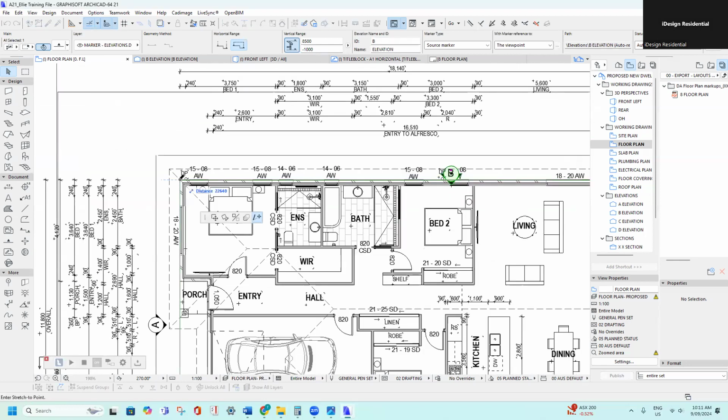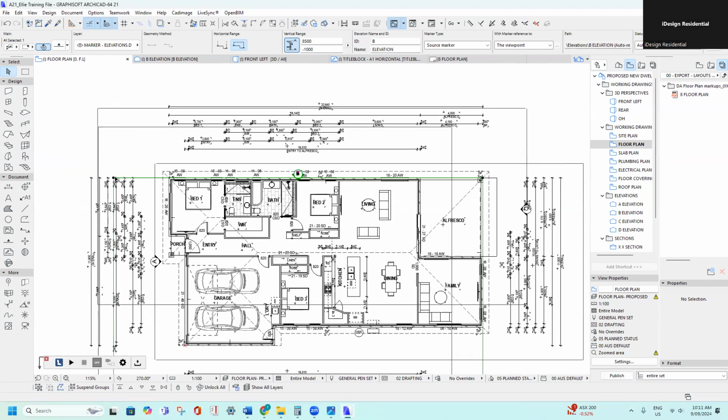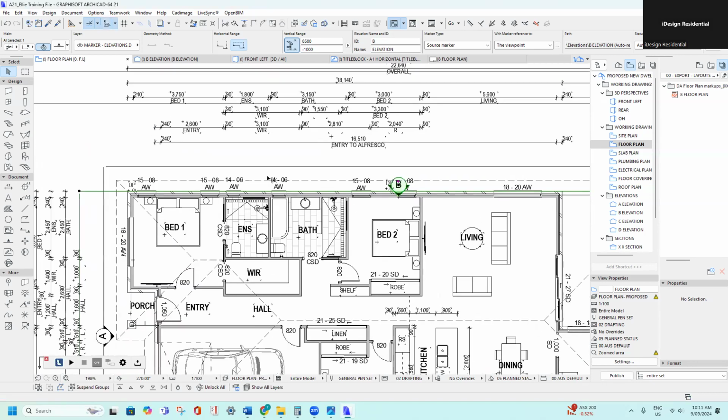and then I add in an extra 4 meters. So you can see the distance is showing 22,640. So I'd add in 4 meters, which would make it 26,640. Enter. And now you can see it's 4 meters extended to this side, and it's flush on this side. I want to even that out. So I'd press Control D, hold Shift, press R, move it over 2 meters. Okay. Enter, and then Control D, I'd bring it off 1 meter.